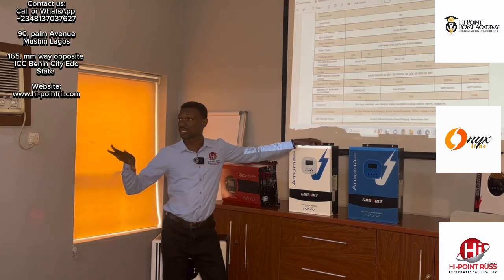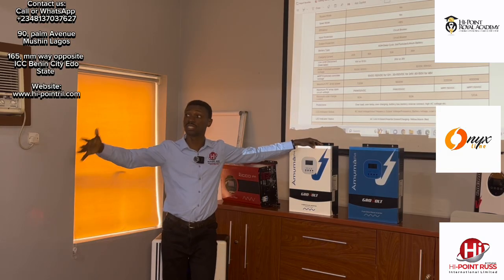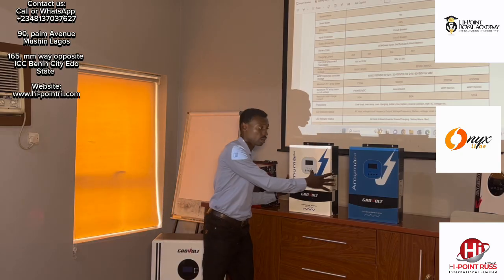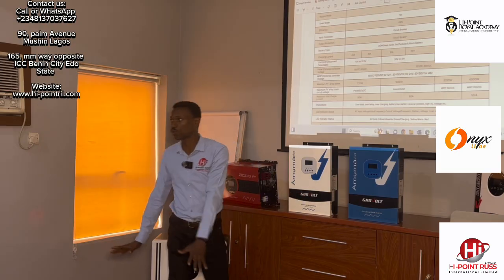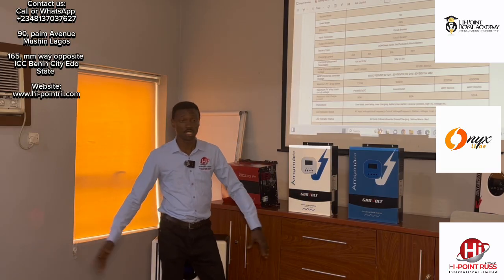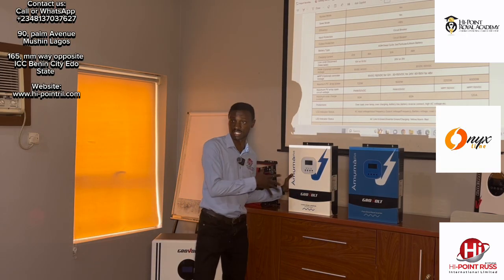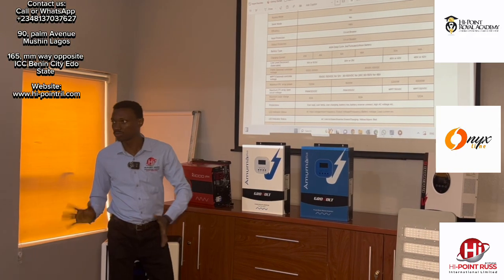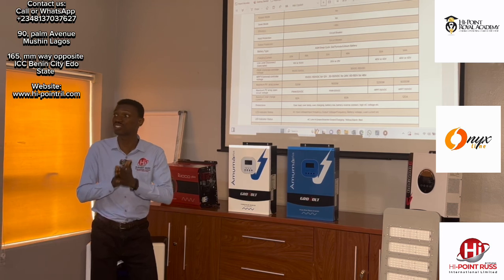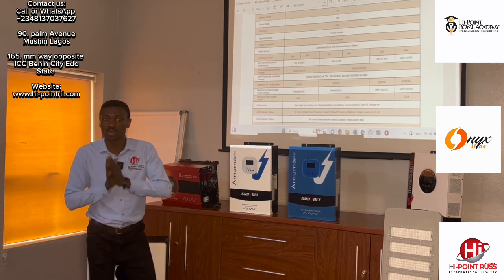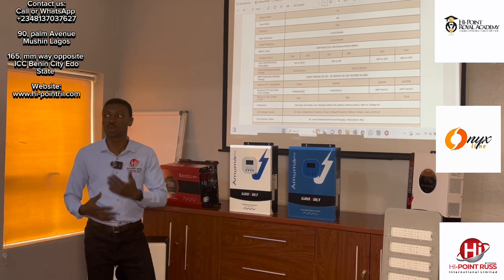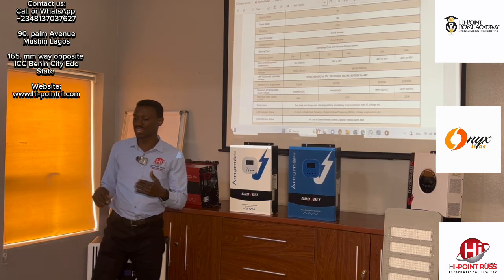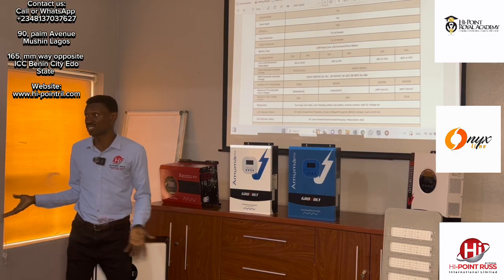We work with lithium in the sense that if that battery is depleted, it will take the exact voltage in it. For as long as this is a 24 volt inverter, you give it your 24 volt lithium, it's fine. If it is a 48 volt inverter, you give it the 48 volt grade lithium, it's fine. It will drain that battery accordingly. It will give you the amount of energy you need, and if the battery drains to the very end, you can charge it up. It will charge and wake up. Most inverters don't really have that wake up function. If the battery has drained to the very end, you'll be stranded.